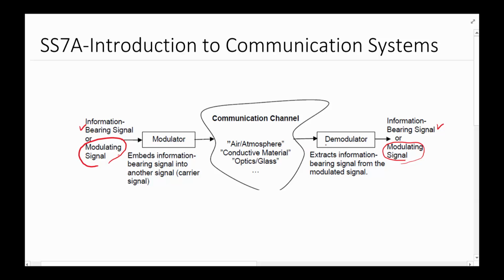And then once the signal is received on the receiving end, we have to take it back to the original set of signals, and that process is called demodulation. You may recall that when you get, let's say, a cable modem, the modem name comes from the fact that it has modulation built in, because it has to transmit things from your side, and it also has demodulation built into it.